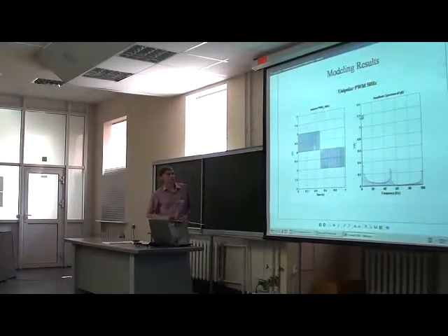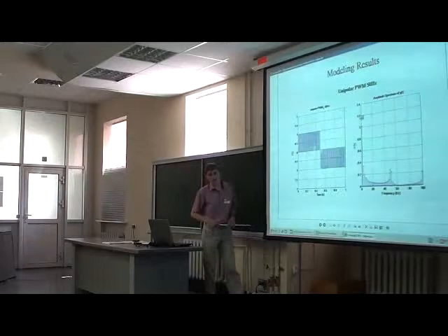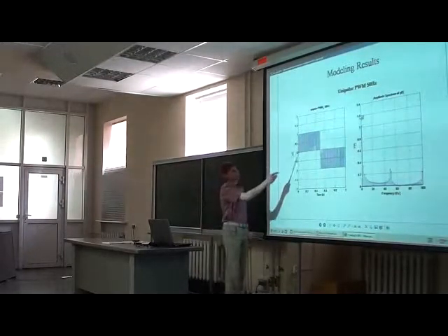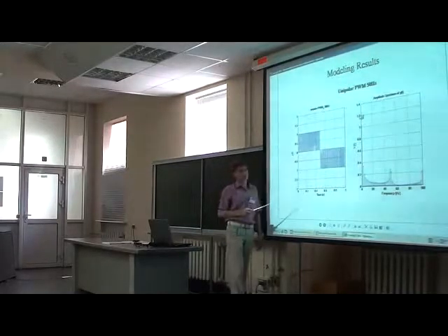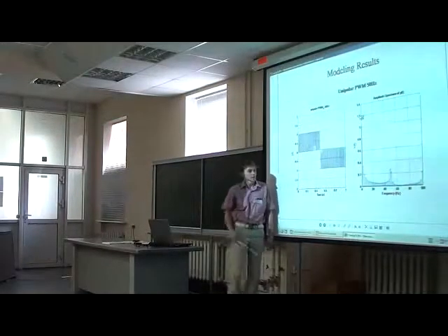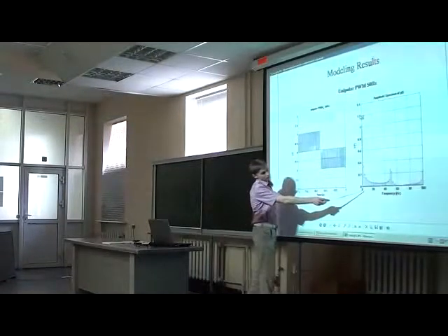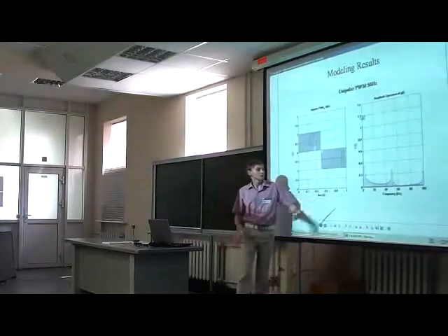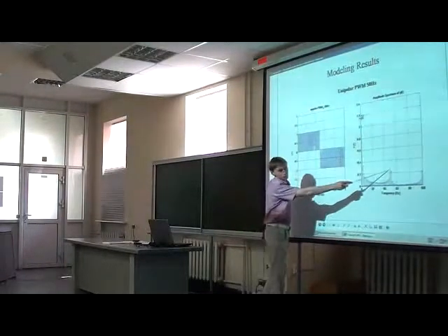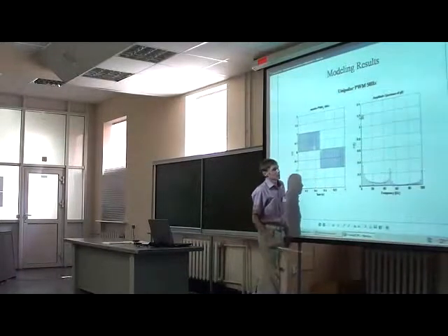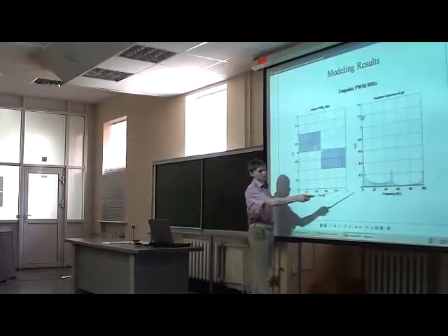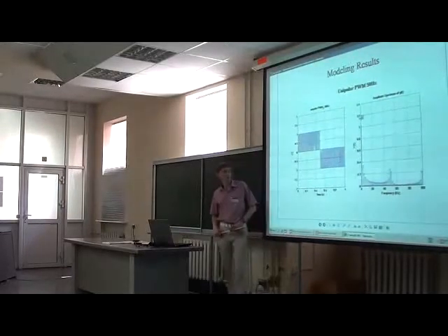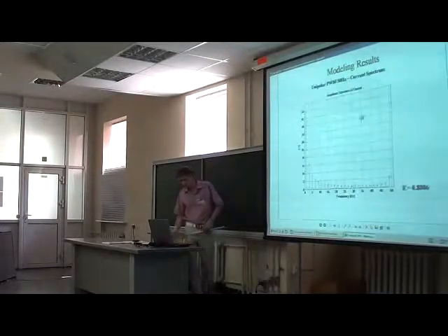In the unipolar mode, we generate PWM. PWM is pulse width modulation. A pulse width modulation signal with frequency 50 Hz. The frequency domain is shown on this picture. You can see this 50 Hz. Here also we have third and fifth harmonics of the signal. It's also not so good.